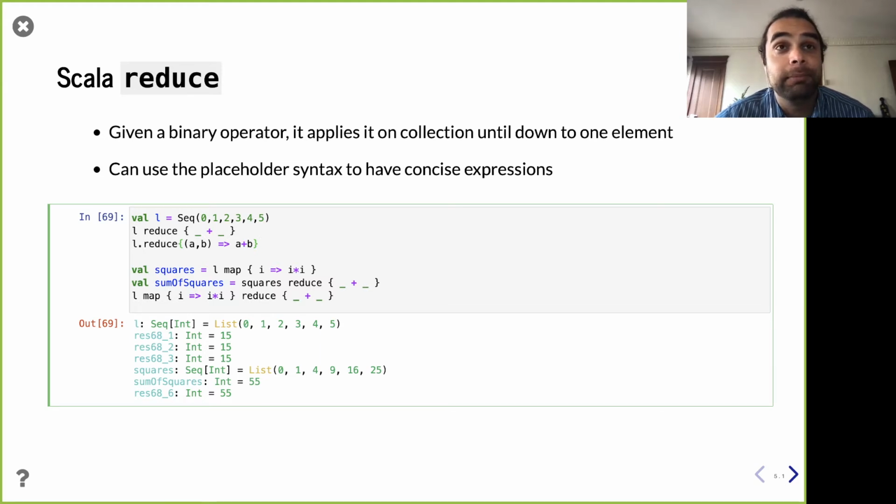However, if these were binary operations where there's no possibility of losing anything, actually the tools could do this. And I think not so much Firrtl, but the downstream CAD tools, I'm sure, would optimize the heck out of it. So it's one of those things where, don't worry about performance until you have to. In this case, the linear thing versus the tree, the two topology choices, are actually similar amounts of hardware. It's just a question of how it's arranged for critical path concerns. Until you have a critical path problem, I wouldn't worry about it. In this course, we don't really push through downstream CAD tools, so critical paths don't really come up, so I wouldn't worry about doing the tree for now. But you should be aware that a tree is going to be more efficient.